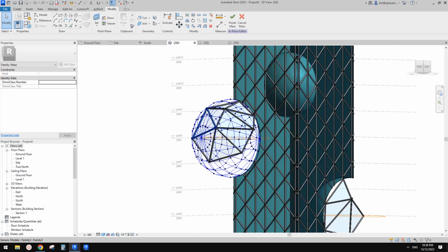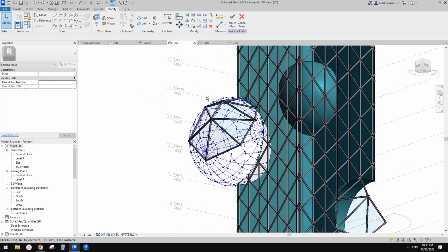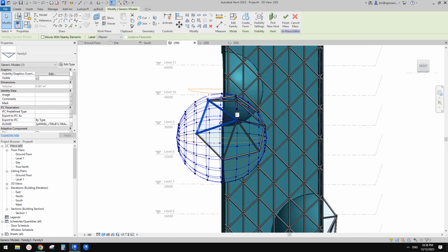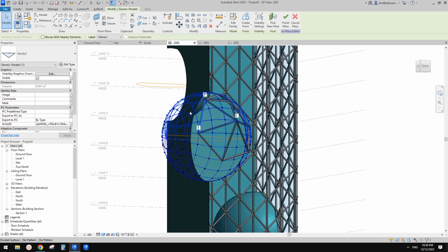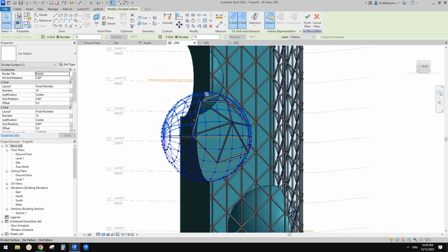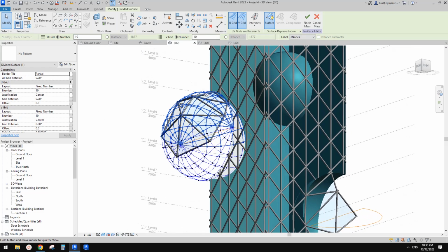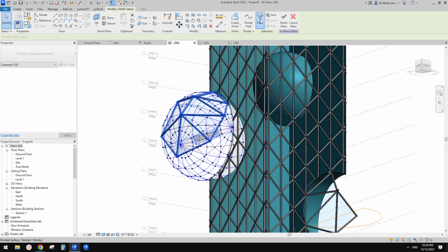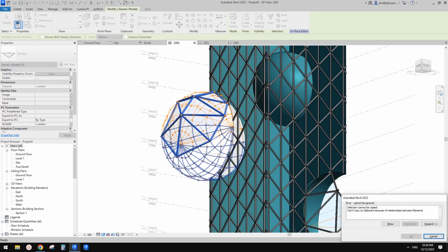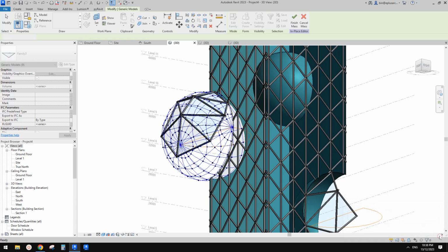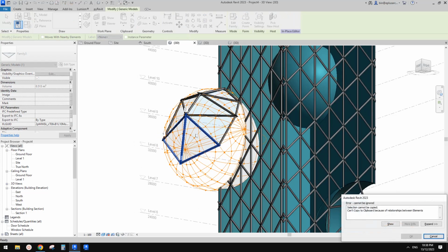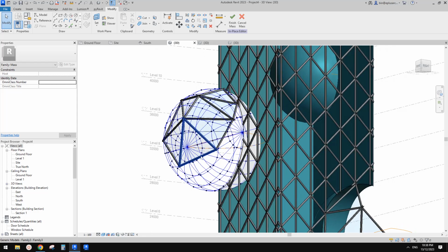This can be an issue, but I think you can probably, because currently these adaptive points are snapping onto this divided surface. So if you delete the divided surface, it will also delete the adaptive family. But I believe you can select them and Control X. Oh, doesn't work. How about Control C? Doesn't work either. Looks like we have to.